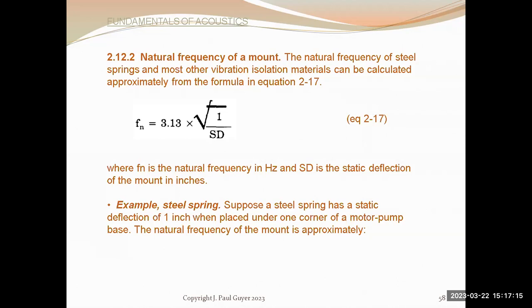And so you would plug in what that static deflection is into equation 217. And that would tell you the natural frequency, as an estimate, of the fan and spring combination.